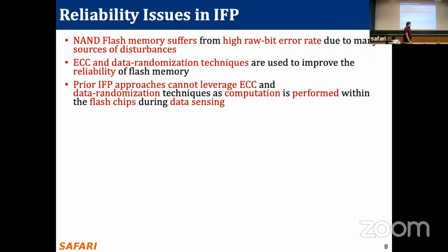But these in-flash processing techniques cannot use ECC and data randomization techniques because the computation is performed within the flash cell and within the flash chips, during data sensing.